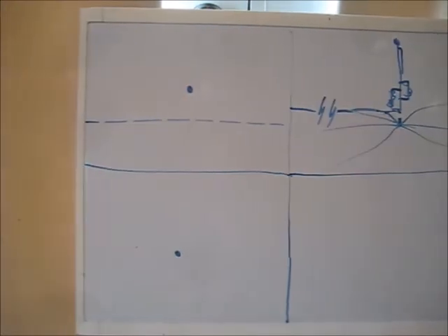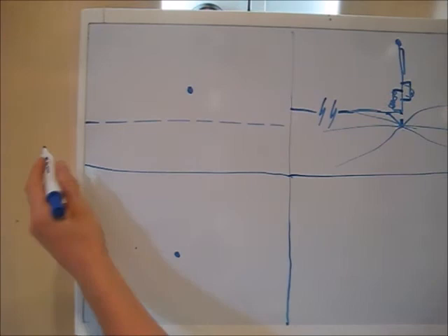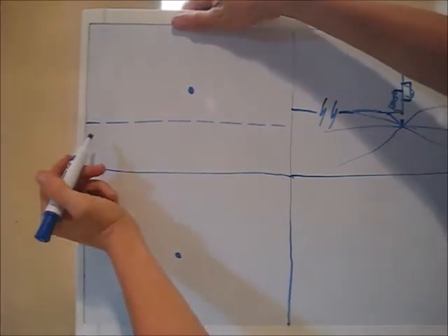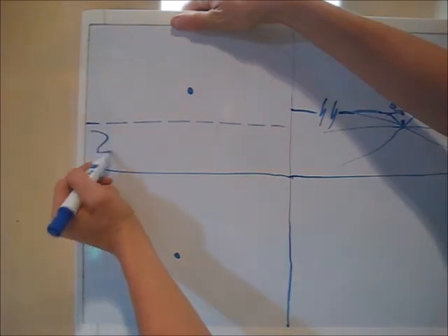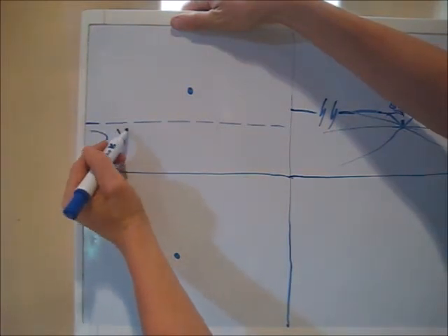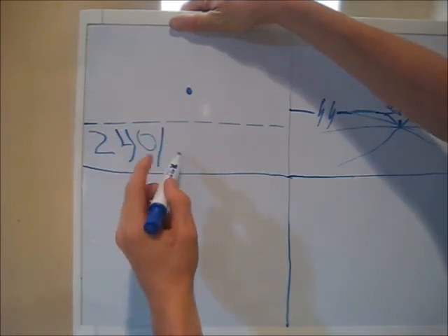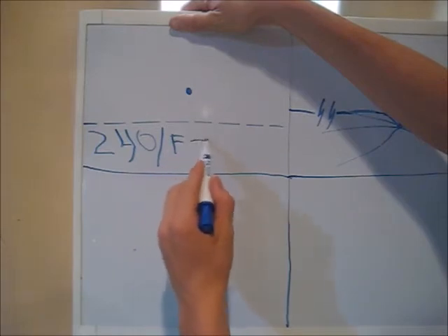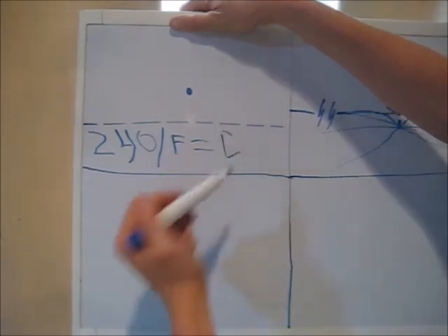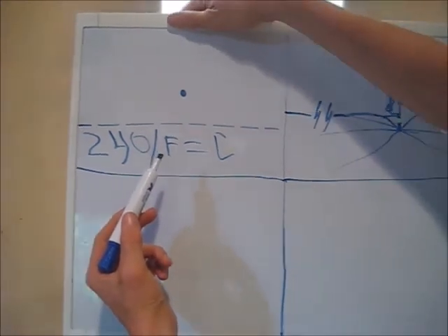So how to make a vertical? The easiest way to do this is to use a simple formula very much similar to the one I mentioned in the dipoles a minute ago. This one is half the size of a dipole. It's 240 divided by frequency in megahertz equals length in feet. That is how you calculate your radials. That's a resonant radial for you right there.